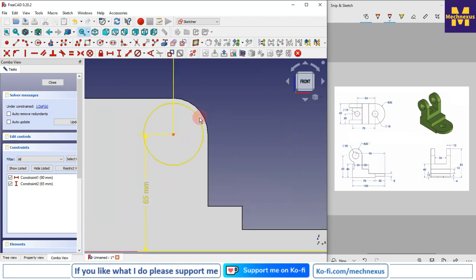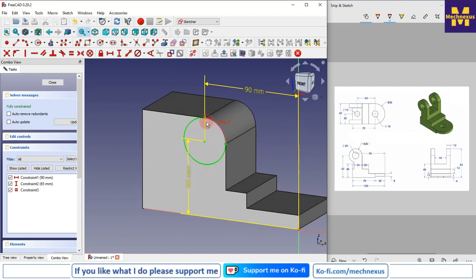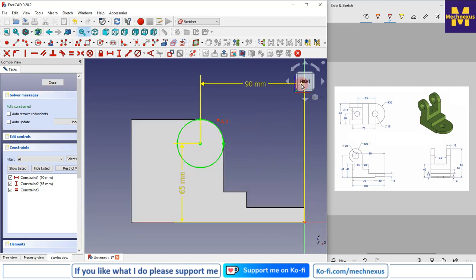We can give a dimension, or we can simply make it in relation with this. So instead of giving a dimension, I will make it equal. You have both options: either you can constrain it with a diameter 40 or make it equal. So better I have made it equal, because when this feature changes, this will automatically change. So I would like to keep the dependency on my feature, and we do not require it as a part of our extrude cut.